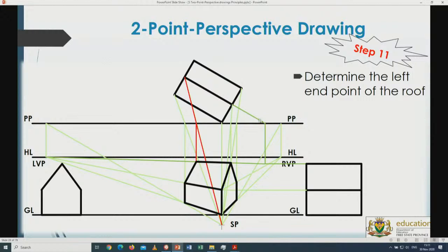Now this principle first runs horizontal, and then from there on it bends up to that vanishing point. So it's extended, going downwards until I reach the horizontal point of that. That's the height. From that height, it will bend. In other words, if I should carry on with this line, it will run parallel the whole time up to that point. It doesn't intersect with the left vanishing point. But now since I've got the intersection point, I bend this line upwards to the vanishing point. So that's where we go.